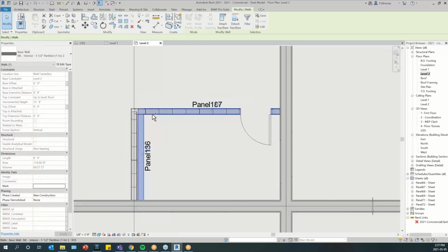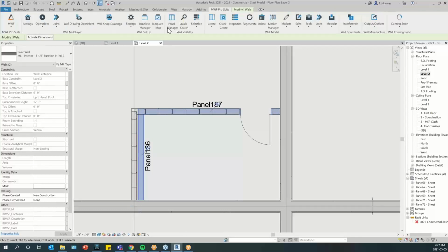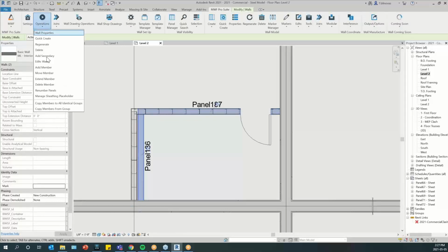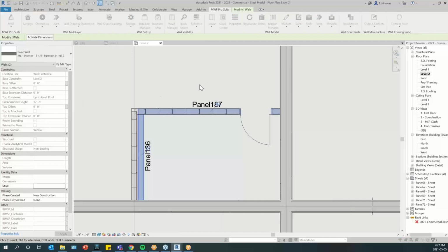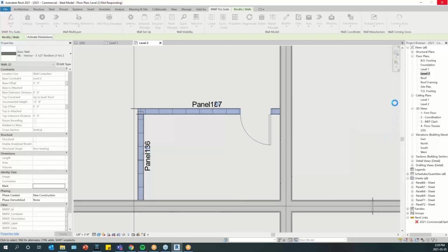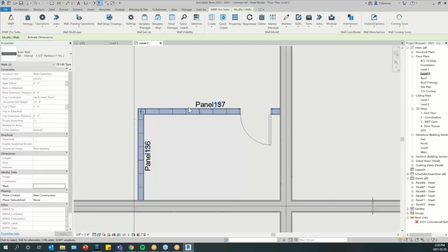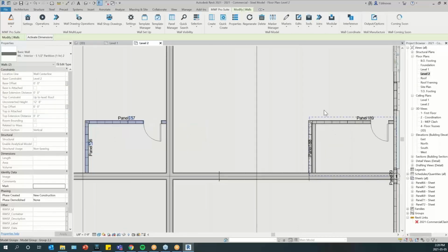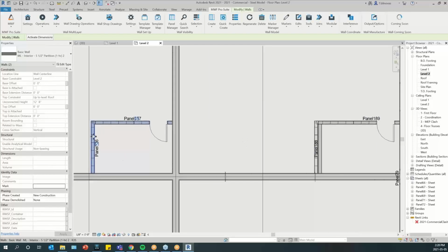You would have to select them like I did before, so you have to tab and manually select each wall. And then, in this case, it's a multi-layer, so regenerate will be here, and then just regenerate. It will work as if it was just a regular wall. The panel will be updating accordingly to the wall profile. And of course, this change will be pushed to the other groups, in case you just have to select the walls and then regenerate the panels again. You will have to do the same process for this one, but it will update just like this one.